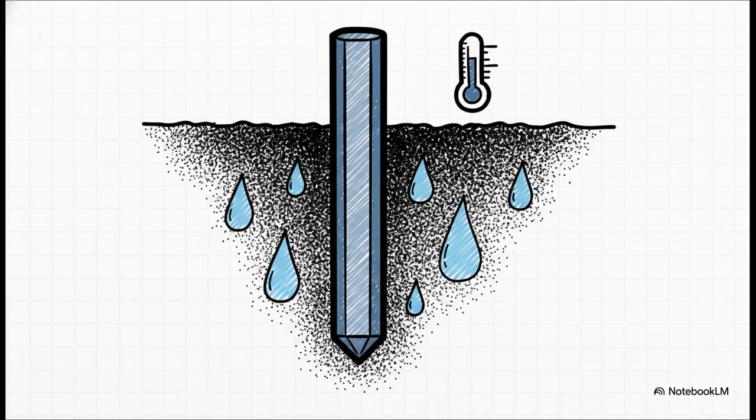But honestly, whether you go with a plate or a pipe, the whole system's efficiency really hinges on the environment. Finer soil conditions, lower soil temperatures, and super importantly, greater water content all make the system work significantly better. On top of that, engineers can boost efficiency by using larger electrodes, spacing them further apart, and embedding them even deeper into the ground to ensure that when disaster strikes, the safety net works flawlessly.